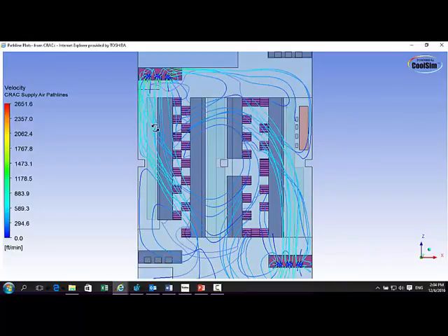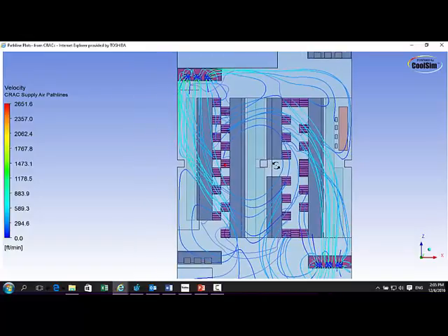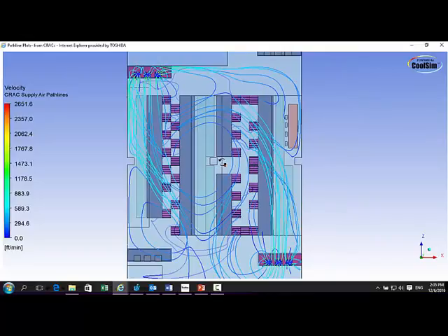You can see the air coming out of the cooling units, coming down here, this air going, of course, this way, and therefore creating a pattern in the center where it's fairly low pressure. Now in this particular data center, it doesn't hurt too much because the perforated tiles are actually here and over here. So this low pressure doesn't bother too much. But you'll see that this tile and another tile over in this region right here are, in fact, there's no tile there, but those areas are going to be lower output than the rest of the room.